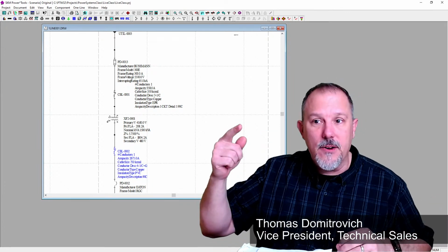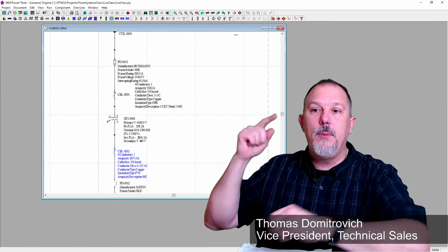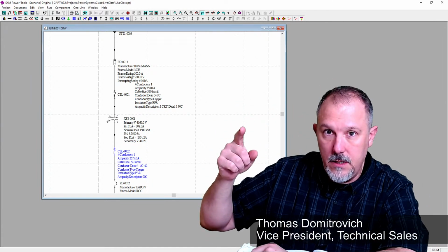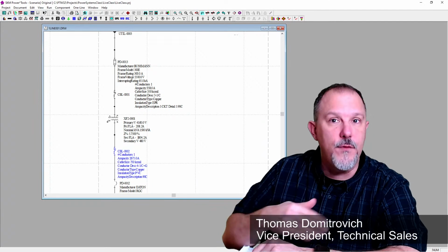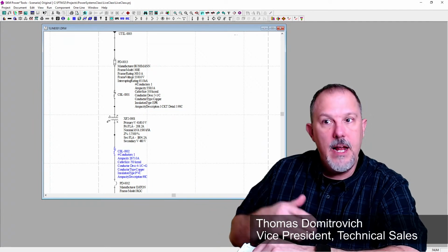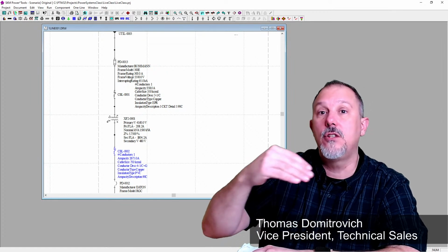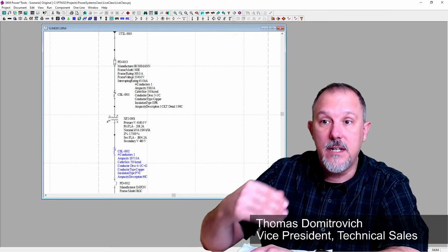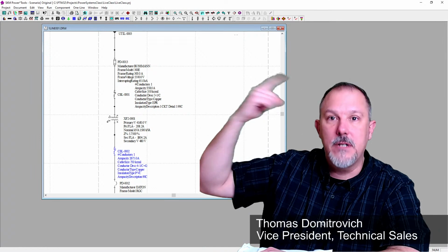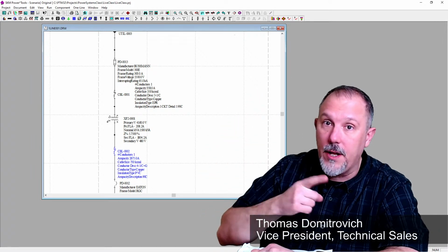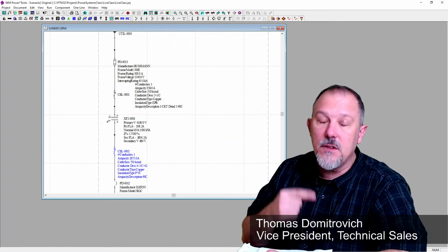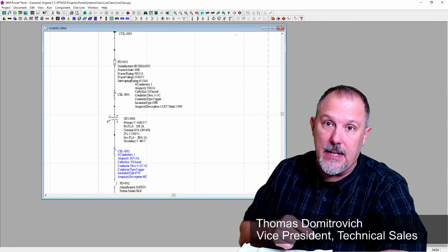But the primary of this transformer, I'm going to pick the overcurrent device based upon the inrush current, not the full load amps. And then I have to make sure that my conductor is not sized to the full load amps. My conductor is sized to the protection, because remember, Article 240 tells me I have to protect a conductor at its ampacity.